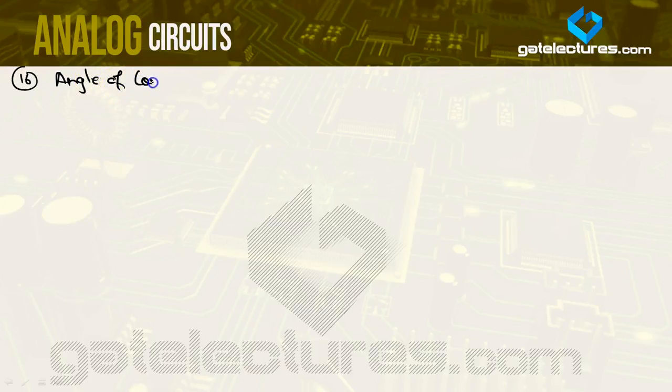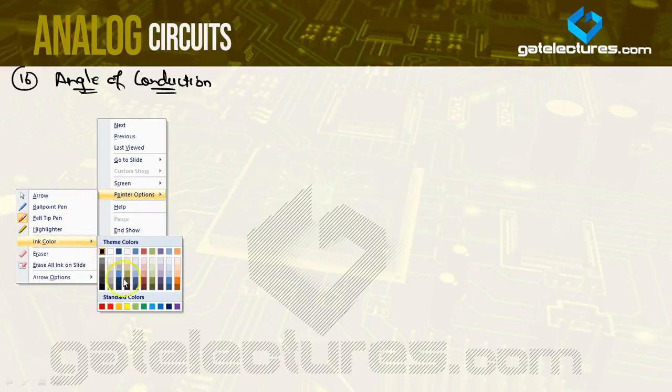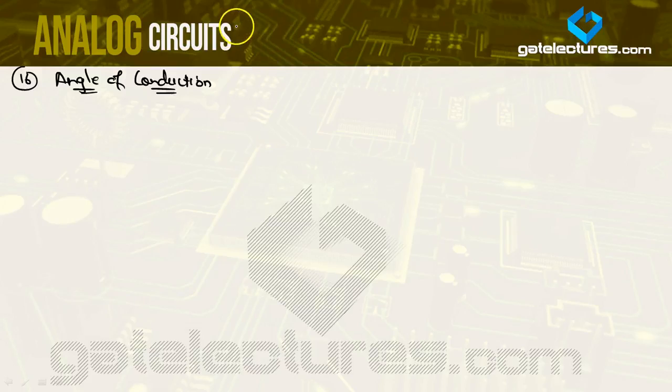Now the next point of discussion is the angle of conduction. Angle of conduction is basically the period for which your diode conducts, and it will conduct only if the voltage crosses the cut-in voltage of the diode. We are not considering an ideal diode. We are considering here a practical diode, and we are only considering your gamma value, V gamma. So it will only conduct when your input voltage crosses V gamma, which is the cut-in voltage. So if the diodes are ideal, we have to basically consider both diodes in this scenario.